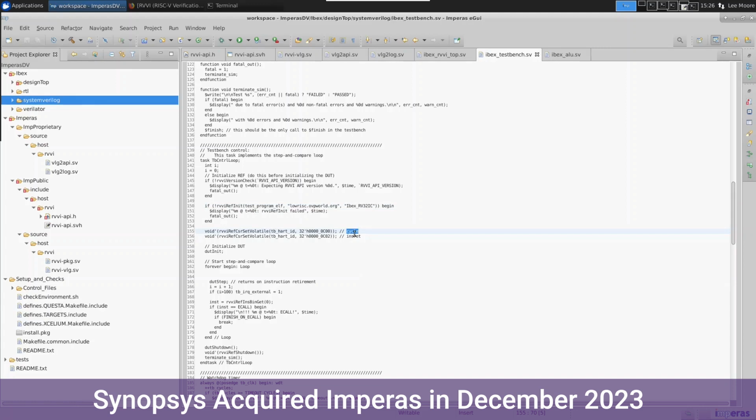Now, volatile doesn't mean that it's ignored or anything, because you have to use this information, because if you imagine you have a piece of code that executes a branch on the value inside of one of these volatile registers, then you have to ensure that that branch takes the correct flow of control based upon the value in that volatile register.